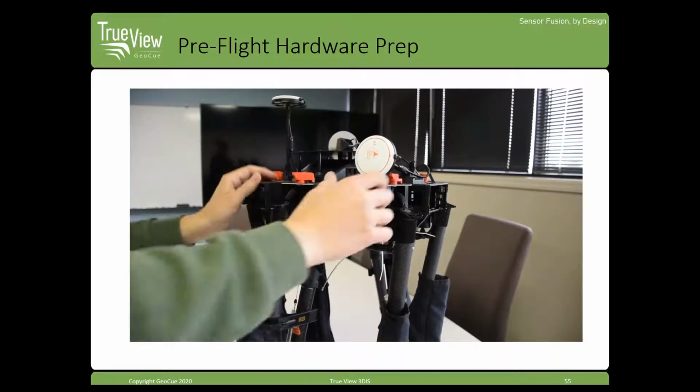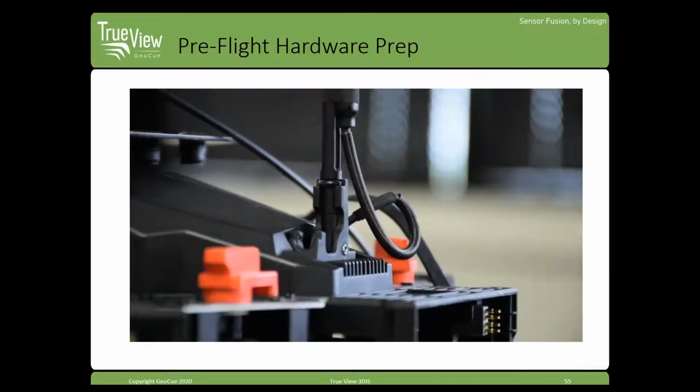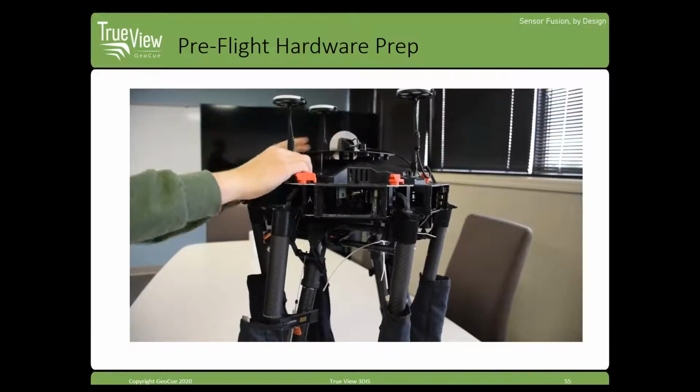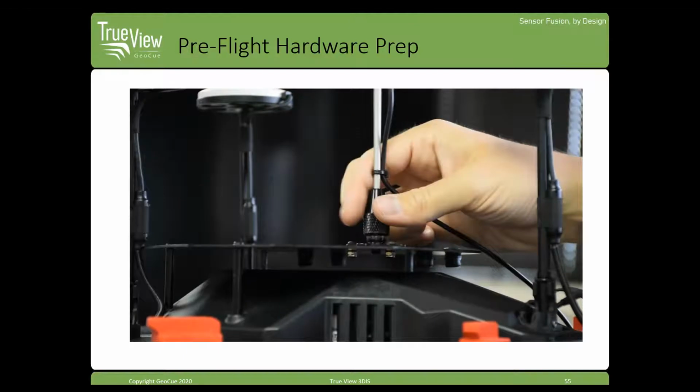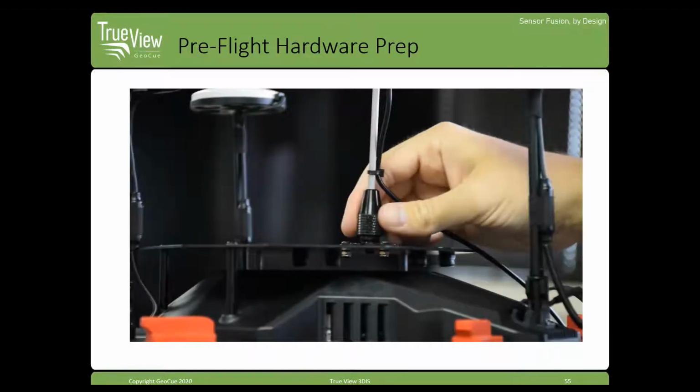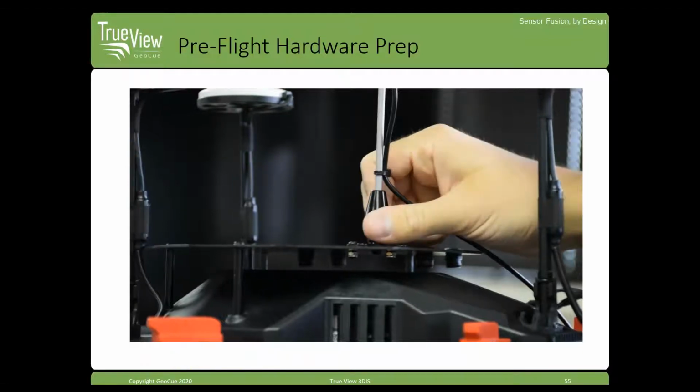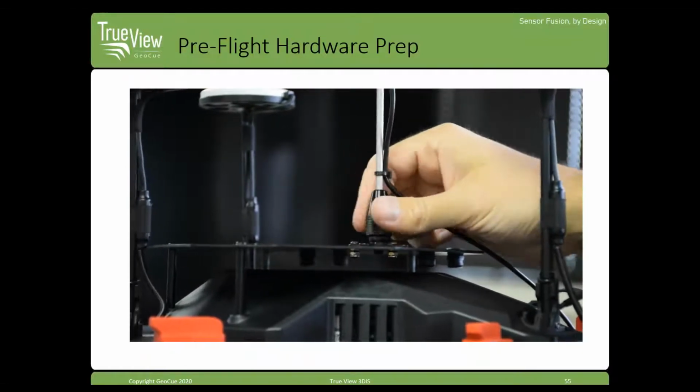So this is an M600, of course. You'll just fold out the antennas first on that aircraft. The newer antenna style is not this screw-in type. It's a piece of aluminum that just sets in here. It's got a base that it just clicks into. That way it's removable, a little bit easier to fit in the case.